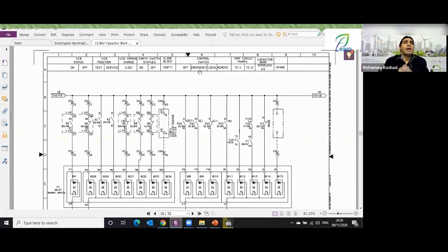Now how does the BCU know whether it will be closed through it or not? You told me about the local, emergency, and remote modes, right? So it must receive the off, emergency, and local/remote modes, so that when it's in emergency or off mode, it indicates that the control is not from it. When it's in local mode, it allows the internal logic to verify, and when someone presses close, it issues the closing command. If it's in remote mode and you press close, it will send a message saying you are not authorized, meaning you are not allowed to close from my side because the relay is in remote mode. It must be received from the SAS.